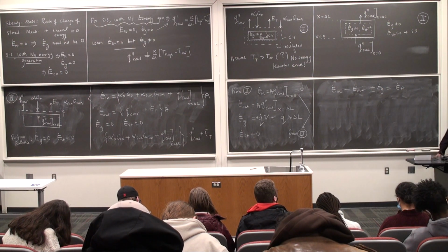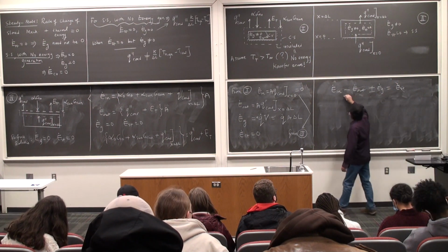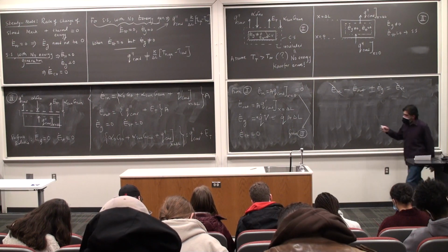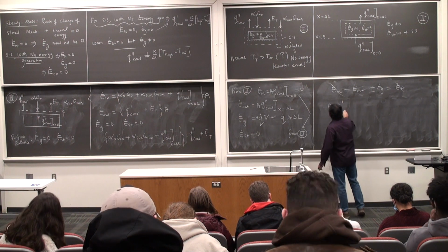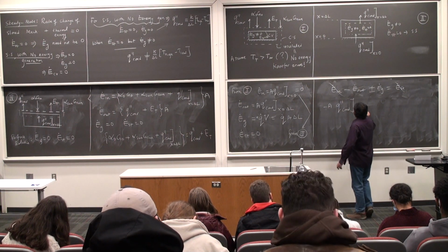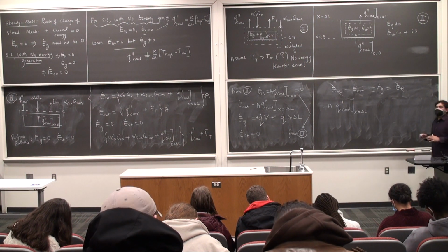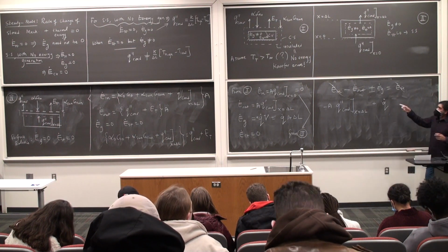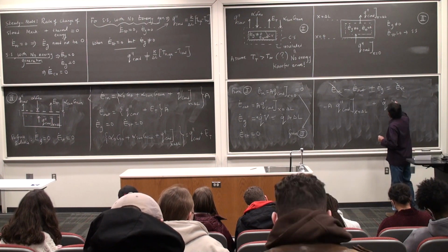Bear with me, last couple of minutes. E dot stored is history. E dot in is gone. E dot out is A times that quantity. So minus A q double prime conduction at x equal to delta L plus E dot generated, which is this new term that you're seeing today, q dot, little q dot. You're going to see that fellow for a very long time from now on.